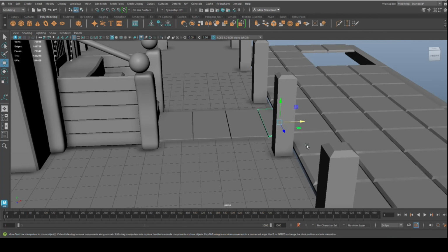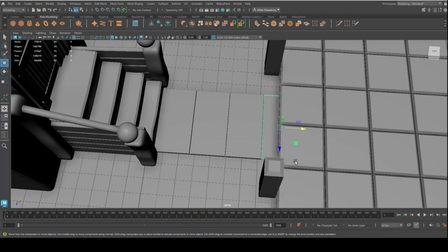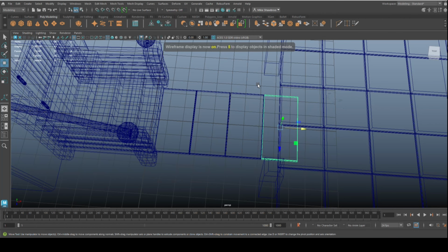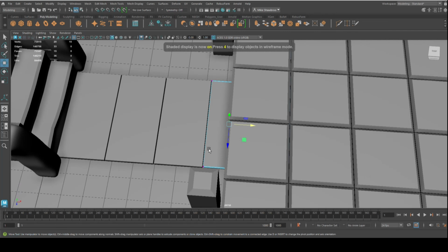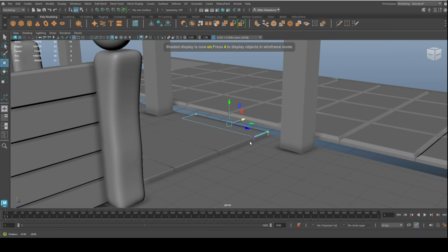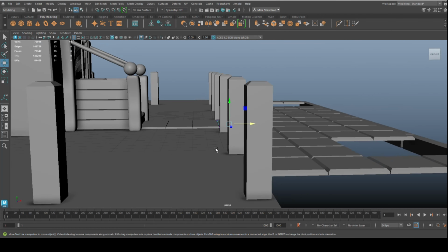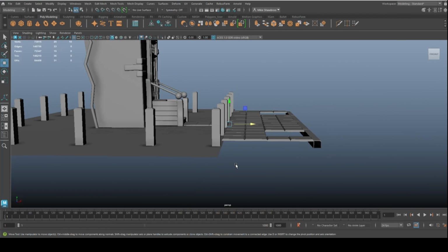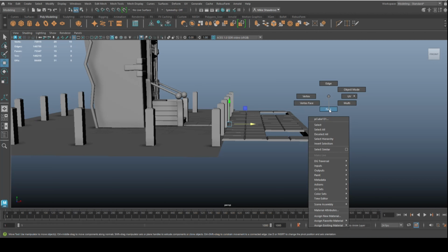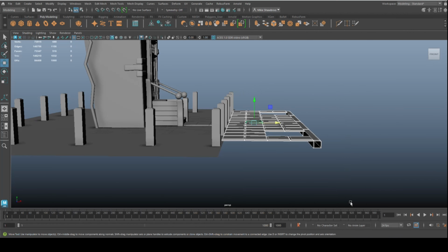And of course, we're going to cut that to size, right? So we're going to go to vertex, drag select, after frame, 5 for shaded mode. So get something looking like that. And I think we're going to lower this whole section here to get everything aligned.